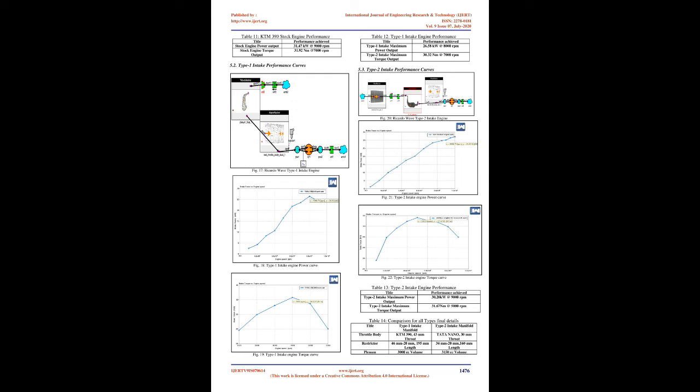This proves that the air pressure generation inside the plenum of the Type 2 intake is much better than the Type 1 plenum, which in turn proves to be better in the higher volumetric efficiency regions of the ECU lookup table, extracting more performance out of the mid to high RPM range of the engine. This volume proves to be good till 91.43% volumetric efficiency of the engine, which is more than enough to extract nearly the full potential of the engine, closest to that of the stock performance.